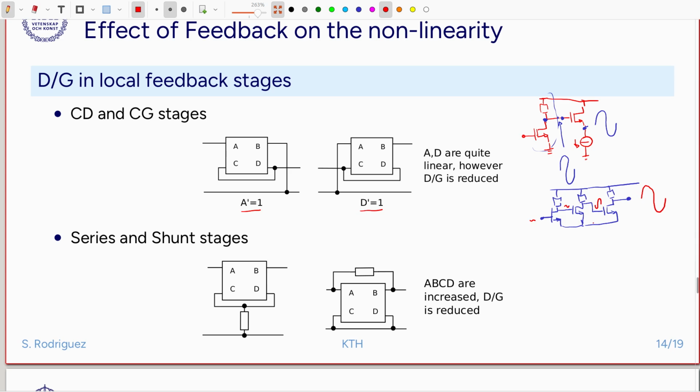So think for a second, the signal swing that we see at the input of the last stage is much smaller, so it's going to stress less the linearity requirements of the last stage, and the second stage also will see less signal swing than the first one.